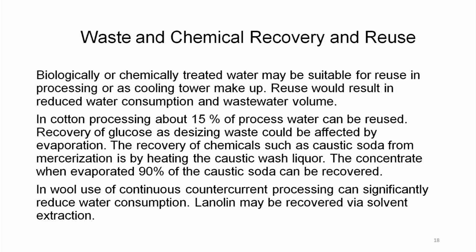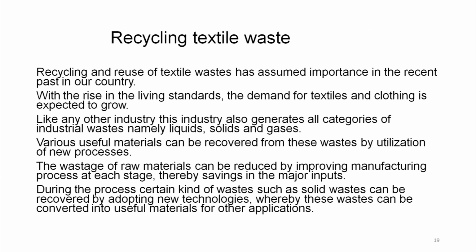So, in cotton processing alone, at different stages they can be recovered. They need not be mixed with the entire textile effluent. Once they are mixed in the entire textile effluent, then the recovery becomes more tedious. In wool, use of continuous countercurrent processing can significantly reduce water consumption. Lanolin may be recovered via solvent extraction. So, there are ways of recovery and reuse.